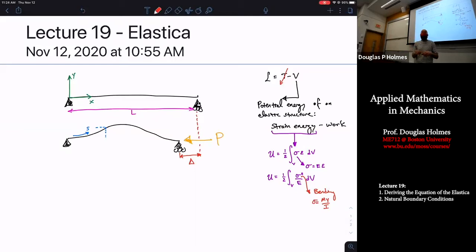And we know, based on the principle of minimum potential energy, that things are going to take the path of least resistance. And things are going to bend if it's cheaper to bend than it is to stretch. And so even though the strain energy could consist of stresses from stretching, bending, twisting, and transverse shear, we're going to ignore all those except for bending and say, really, this object is just bending. And we're going to make that assumption a bit more explicit in a moment when we look at the work.